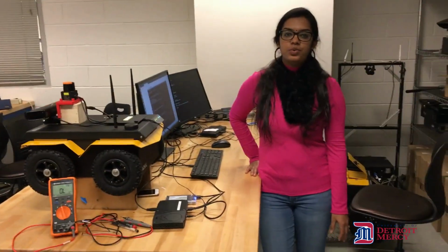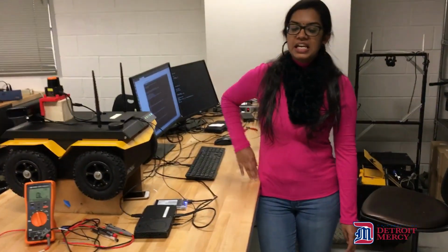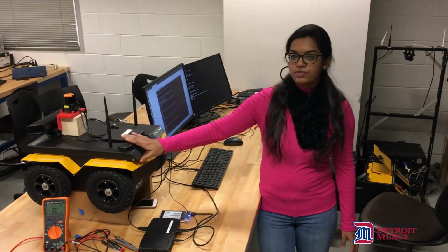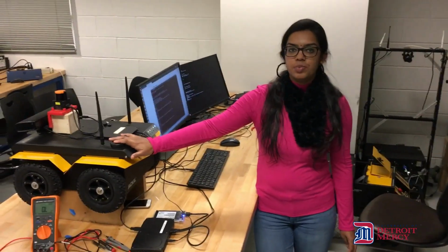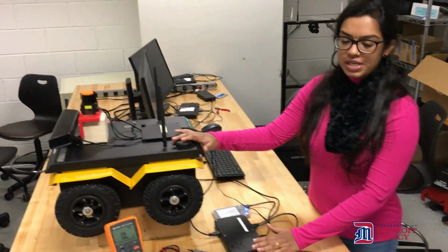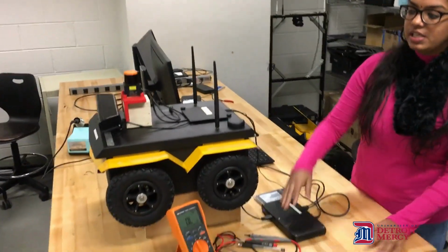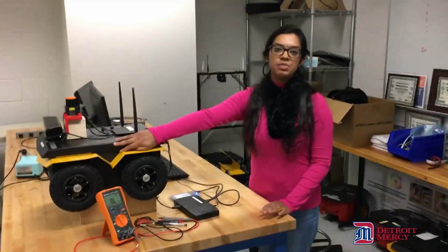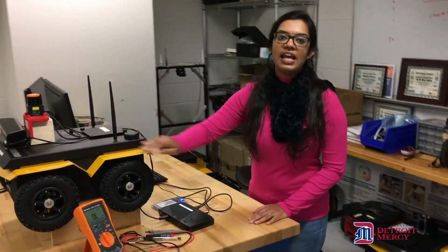As a conclusion, we can now understand that it is because of improper ground between the NUC or the laptop and the chassis of the Jackal that is causing the problem. So if you properly ground the connection between the computer that you are using and the Jackal board, this problem can be easily solved and the mission is successfully accomplished. Thank you, guys.